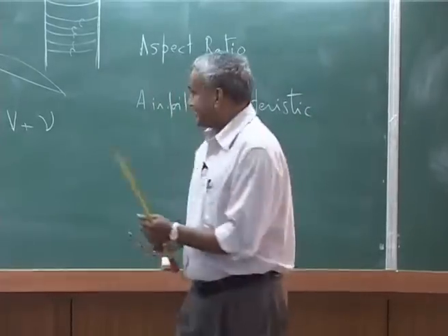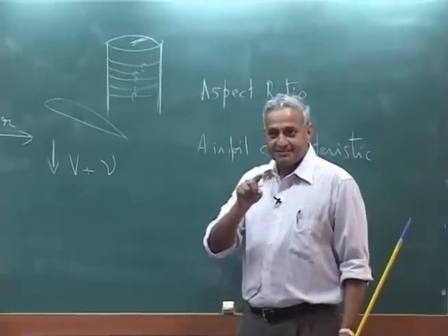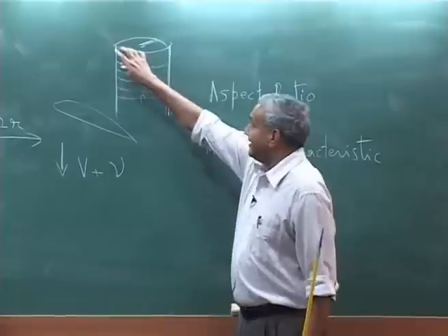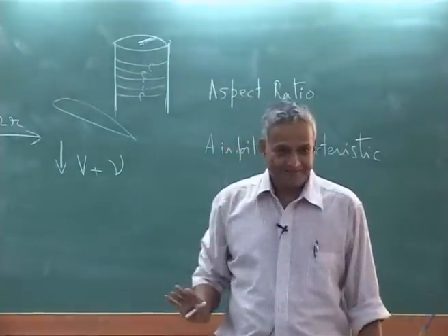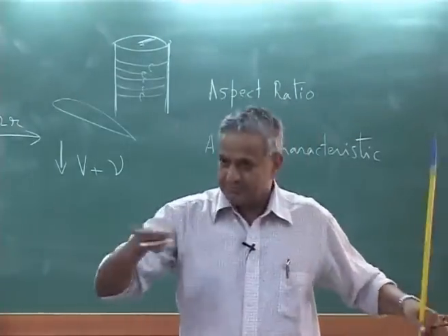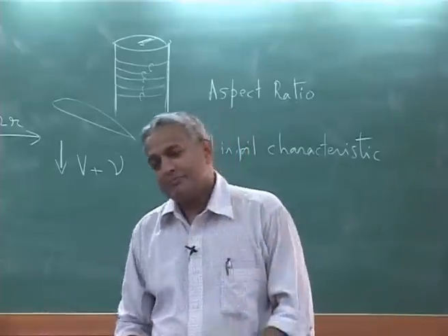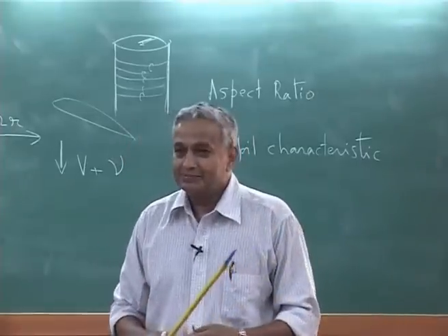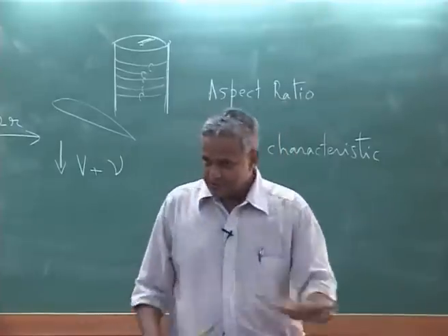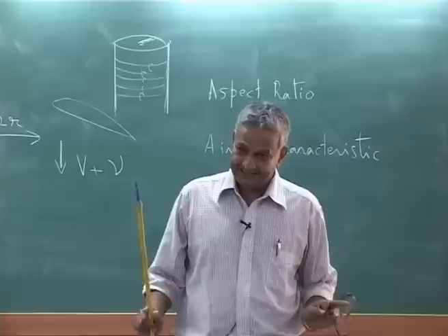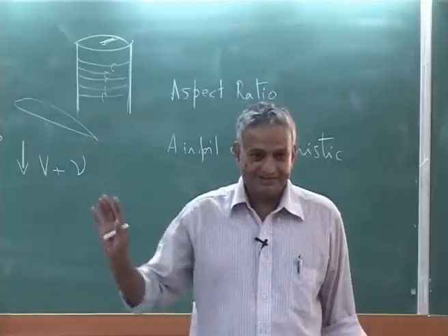When you use a cylindrical wake like this, the induced flow calculated by this approach at the rotor disc is the same as momentum theory, uniform loading. You take that, then you get the same result. So momentum theory is not all that bad. So we use momentum theory in this course. Please understand, momentum theory is even today used in research.